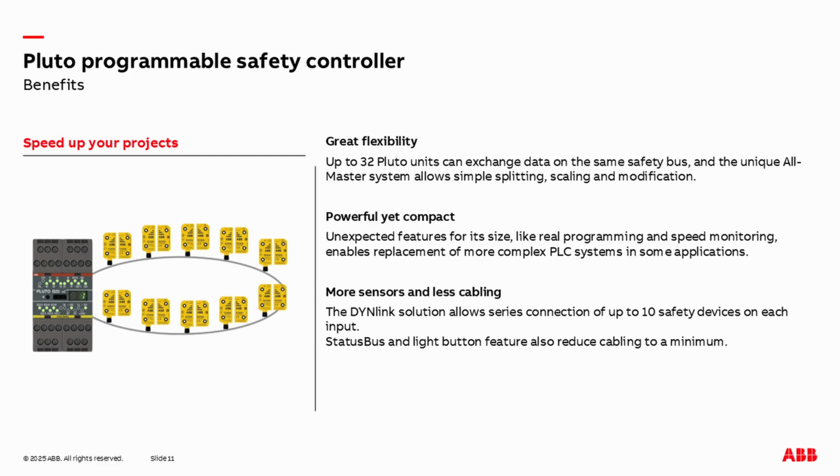And it's what we call an all-master system, which means that if one of the units goes down, the other units will continue to operate if possible, if they're independent of the one that stopped working for some reason. It also makes it very easy to split or scale or modify. And as you can see, it's quite compact, and the DIN link and also to a certain degree OSSD loops is possible. And in the B20, the theoretical maximum of safety sensors using DIN link is 150. So that's quite a lot of power in this little box.